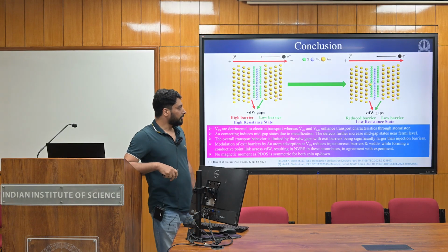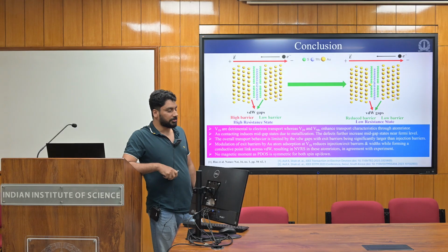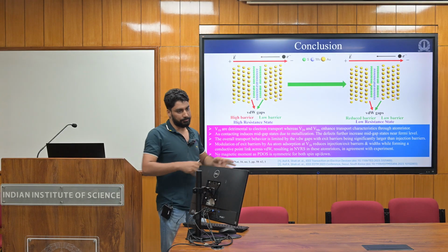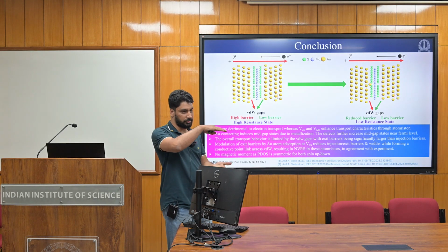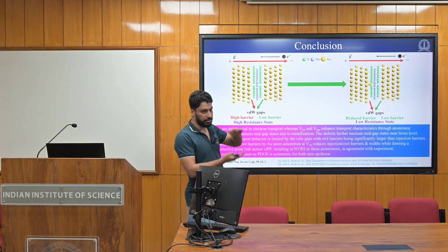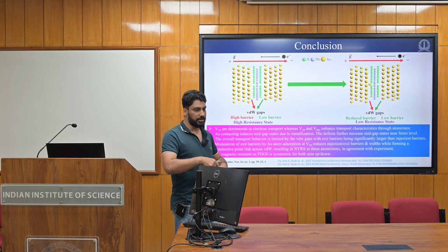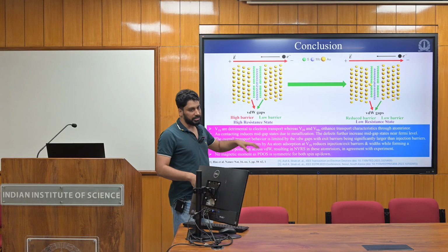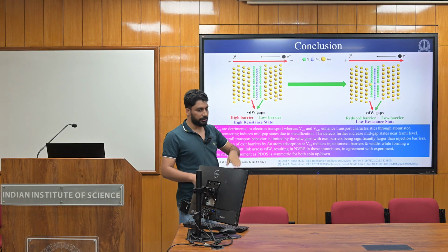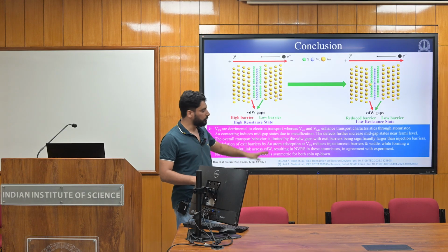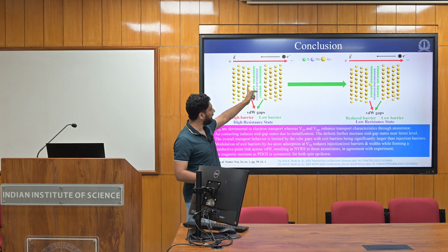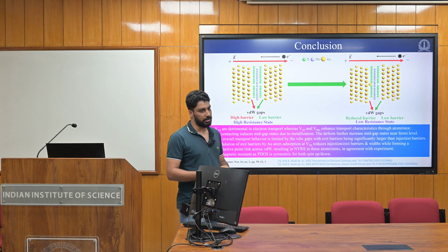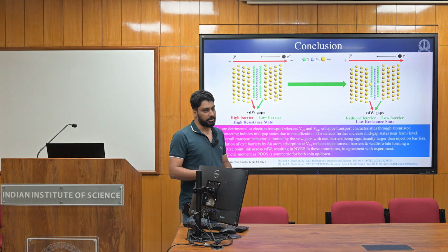Cycle to cycle variability is an issue in these devices. That's why these devices are promising, as they can improve that. Why? Because when you have a thicker insulator, for instance, a thick oxide instead of this 3 layer, controlling these channels at each cycle is very difficult. But here, since the conduction is happening just because of one atom, if you can properly engineer it, then the variability will reduce. It will not be eliminated, but it will reduce, because you only need to control how one atom is moving in and out of the sulfur vacancy. So by properly engineering the defects in the device and choosing the required defect density, this can be reduced, but it cannot be eliminated.